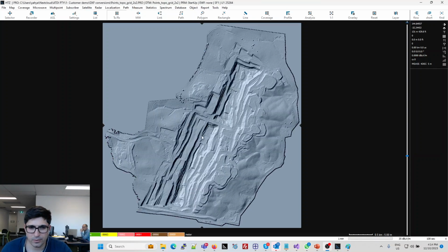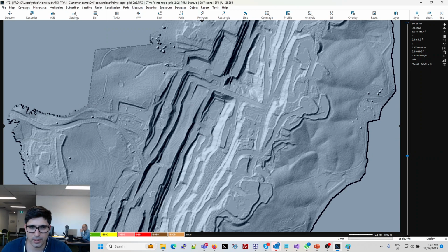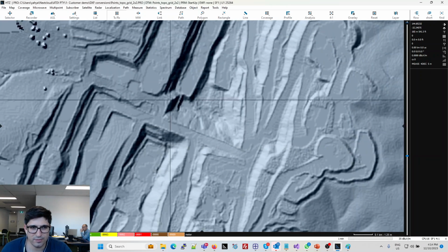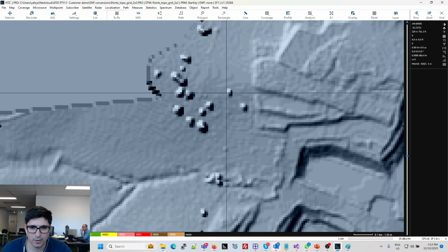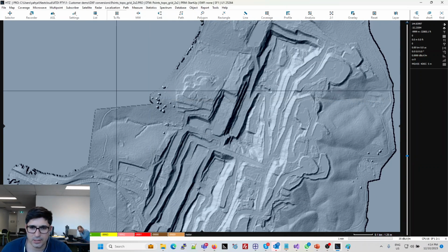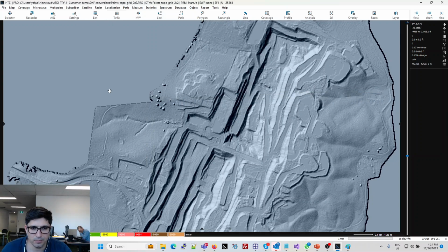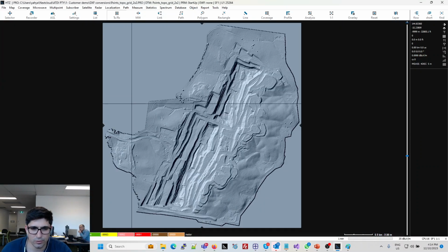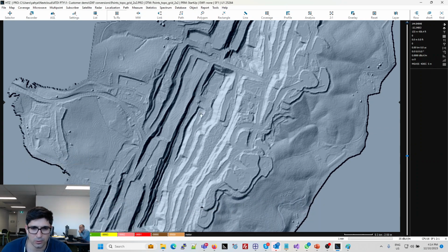It's done. So you see, this is the digital terrain model, and I don't see any gaps. If there were gaps, it would show up as probably something like this. This elevation is what? There's no 0. 225. Oh, they look good. This here is a gap or 0. Obviously, there's no data here, so void. And here you actually have data, so it looks all good here.